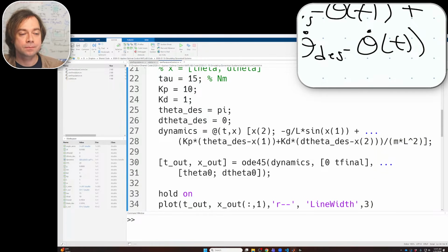Now, as a general rule, if you take controls 1, the derivative gain, its job, it's acting like a damper. It slows things down. So if you want to slow things down more, you make it a tighter damper. How do we do that? We change the Kd gain to be bigger to make it tighter.